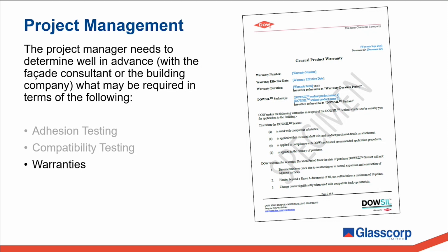The one point that I will make is the importance, again, of knowing what's required before a project starts. So some warranties will require us to carry out on-site testing to validate adhesion and joint fill, which is difficult to do if we only find out about it after the project's already completed, which does happen sometimes.